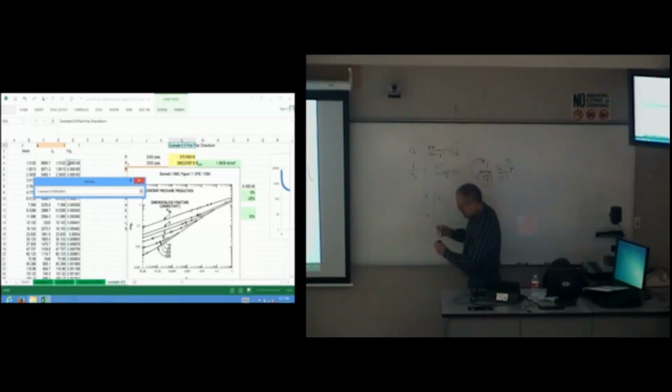And I'm going to do this in black. For a drawdown, it's pseudopressure initial minus pseudopressure of the well flowing, and this changes. You draw a well down, the pressure draws down.